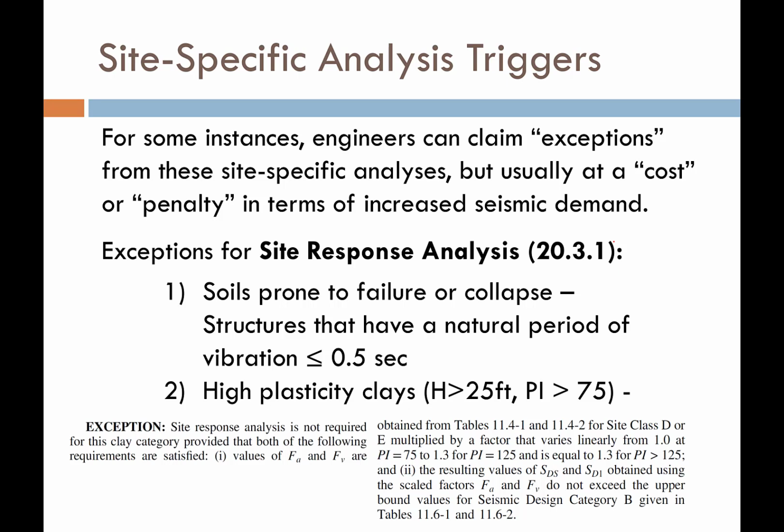So here are the exceptions to getting out of doing a site-specific site response analysis. And this is from section 20.3.1 of ASCE 7. Here are the exceptions down here. So, basically the site response analysis is required when you have site class F soils. And we already talked a little bit about these. And like I mentioned earlier, they are technical in nature. So the first, of course, is if the period of the structure is less than half a second. So this would be like a short, stiff structure.